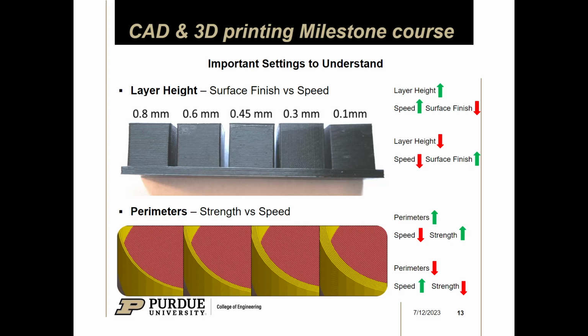Yeah, so filaments, there's a bunch of different filaments out there. By far the most common filament that you'll see people printing with right now is PLA. It's basically a recycled material made from corn, and it's really easy to print. The prints can come out really nice with minimal tuning. But it has a really low melting point, and mechanically it's not as strong as other filaments. So I use PETG, which is slightly stronger, but it's still reasonable to print with.